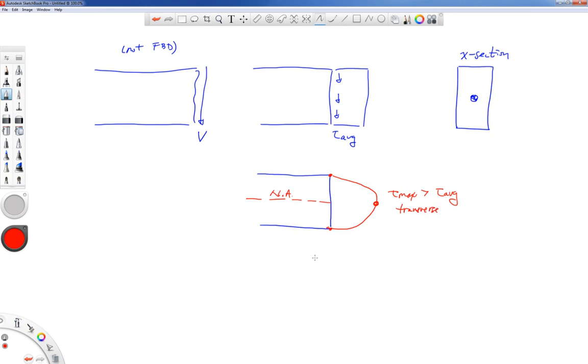All right. Like I said, it's a complicated formula, with some complicated concepts. Just remember, tau equals VQ over It. V and I are easy. t is usually pretty easy if it's a constant-thickness cross-section, or I tell you exactly where to calculate the shearing stress. Q can be the tricky one. Q is a little tough. Q is equal to Y bar A of a shaded area, where you can shade in from your point of interest on the cross-section to the top, or from the point of interest to the bottom of the cross-section, to find that Q area.